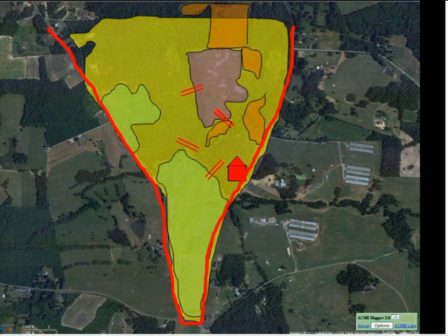Outlying parcels where access via other means isn't available or feasible could be reached by consolidating 3 total crossings into 1 near the house, because it's a site that offers better stability and less maintenance, primarily because of the physical condition of the stream. It's located above a bedrock outcrop at a natural gravel section and requires little maintenance over time.